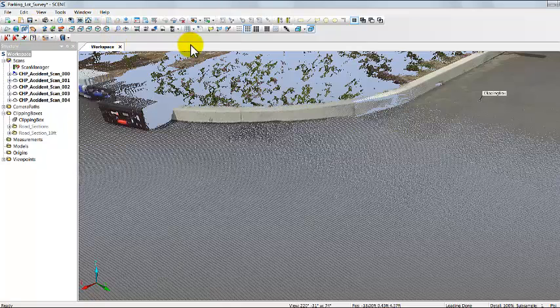And in order to connect the Scene software to AutoCAD, we need to install two things. You need to have the Kubit software purchased, so Kubit PointSense or PointSense Pro, also known as FARO Cloud Pro. And you also need to go to the FARO 3D App Center and install the Kubit Draw-to-CAD plugin. So the plugin is free, the software is a paid software.